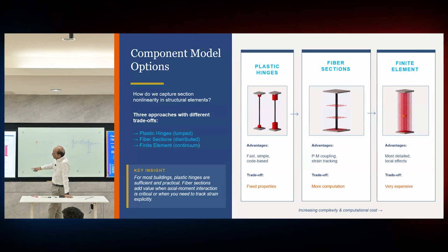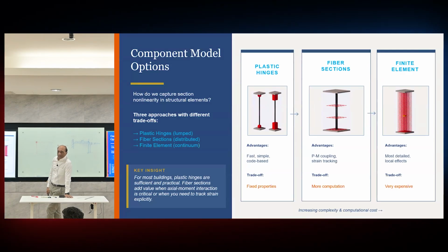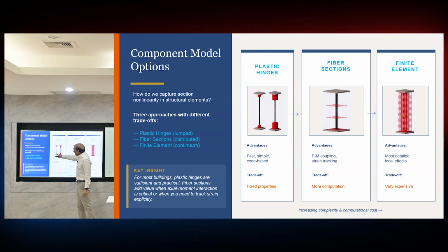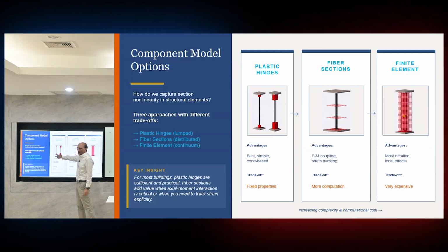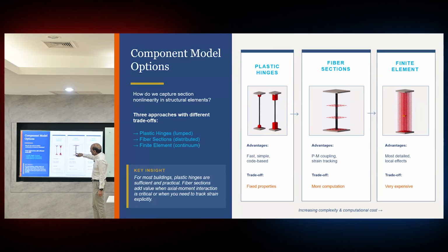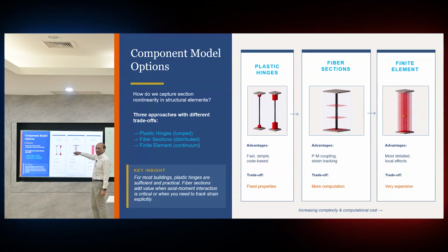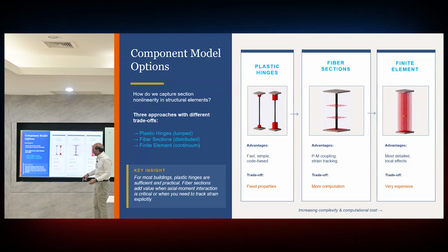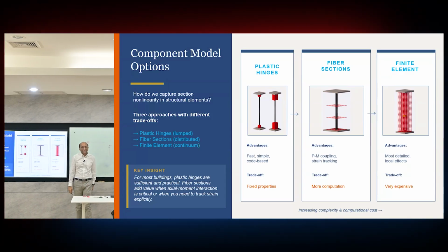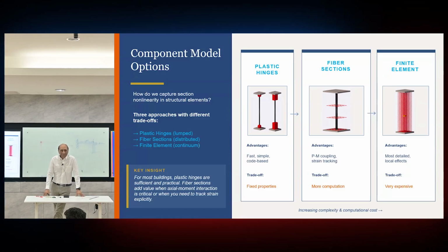So this is the plastic hinge, fiber hinge, and finite element. So that's how the 3 are different. The first one is that you put the fiber hinge at this location with a certain, first of all, just a point. Second one, length, over which it will yield. The fiber section, put many sections and different materials, and then program calculates as is needed. And here, shell elements, and then take every element and put the nonlinearity in every element, in every direction. So that's the most complete nonlinearity that we can do.